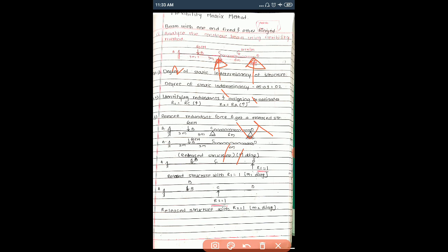Okay, and then what are the known values, or what are the equilibrium equations? Equilibrium equations are summation of moment is equals to 0 and summation of vertical forces is equals to 0. It means we have two equations neglecting the axial force. So 4 minus 2, it will give you 2. So 2 redundants are there, but here I have not neglected, okay.